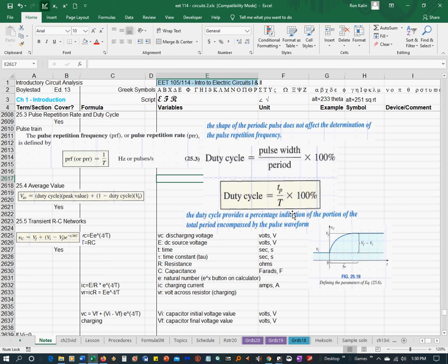The duty cycle is typically over, I think, a 3-hour period, which is the industry standard, but it means how much can it run during, say, a 3-hour period? So if it's 100%, it could run continuously for 3 hours. If it's 60%, it's only going to be 60% of 3 hours, and so forth.